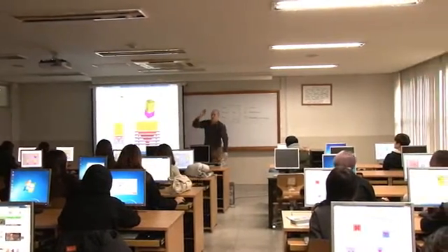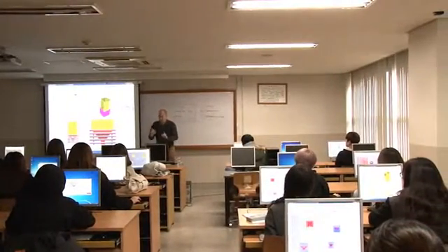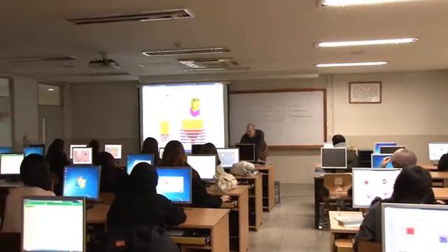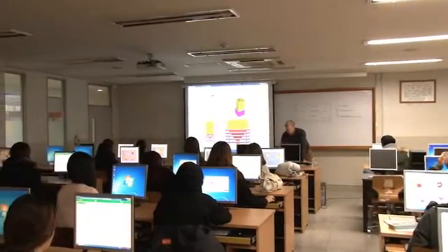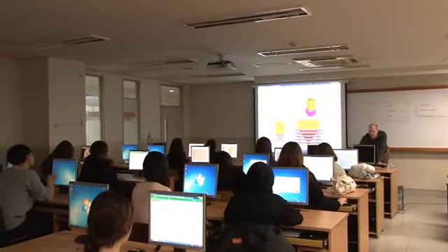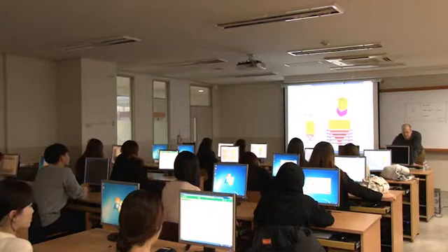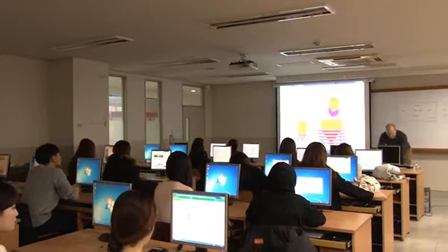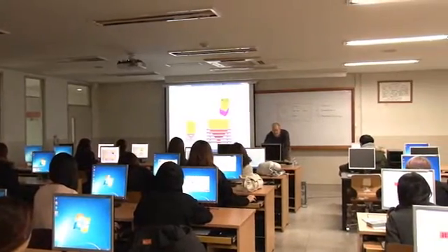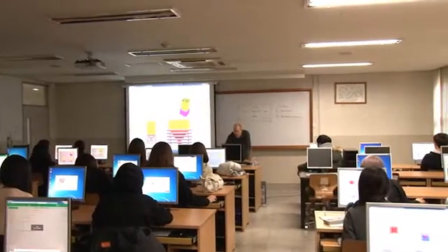just so you know, there's not a perfect algorithm inside of Rhino, okay? And as you can see, we've got these tangent lines here in our perspective view, and we lost some of that here, okay? So, if you don't like that, let's try it again with a slightly different view. Okay, let's move it around. It takes a little bit of adjustment to get this right.